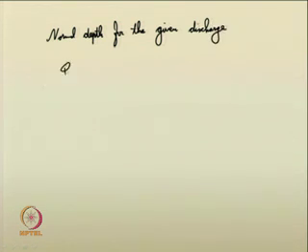Again, the normal depth for the given discharge, you use Manning's equation. Q is equal to 1 by n A R to the power of 2 by 3 S naught to the power of half.